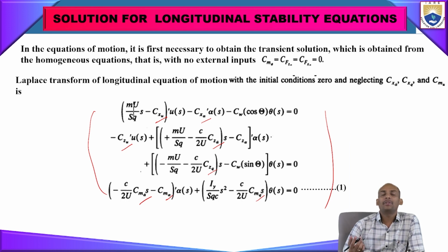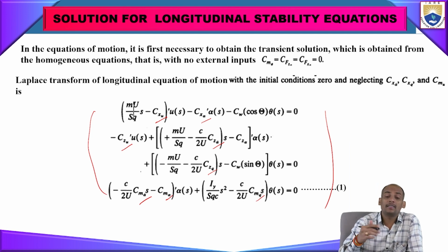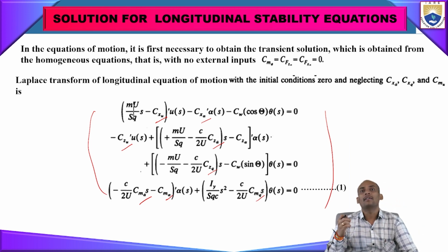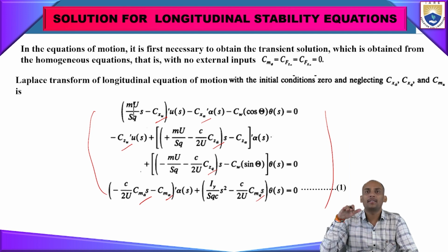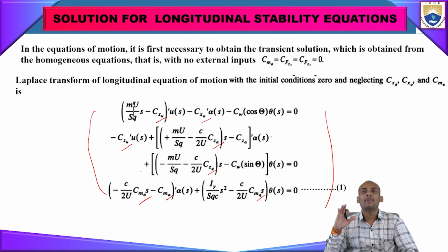In those videos, we explained the stability derivatives by considering the elevator deflection and the rudder deflection and their usage. We also discussed the downwash velocity. The downwash is due to the wingtip vortices, whenever the flow is flowing over the wing leading edges.